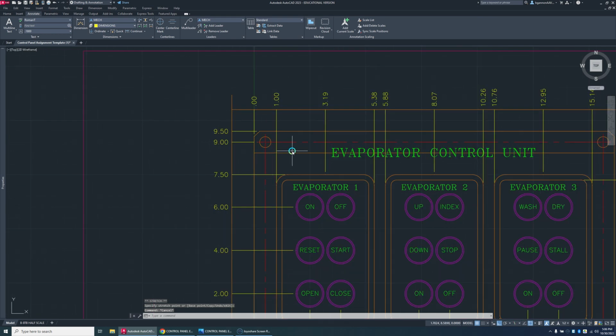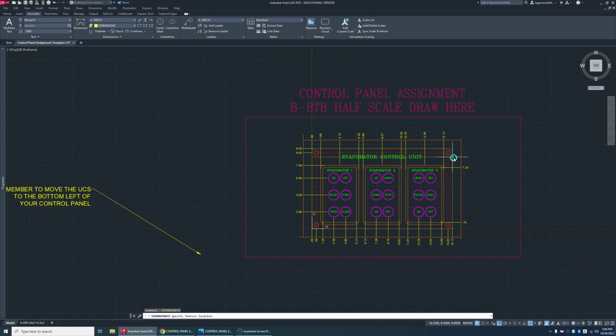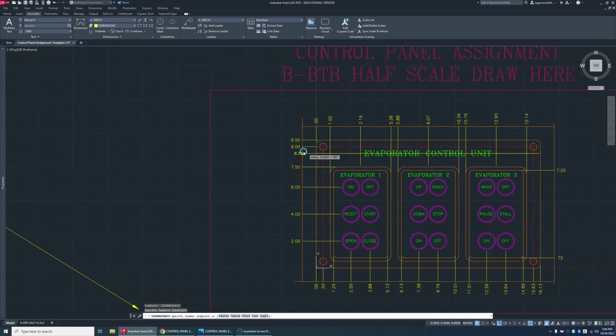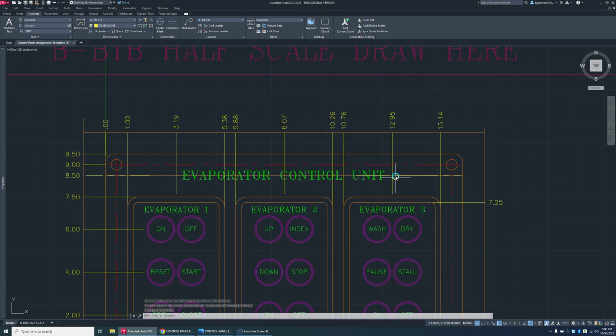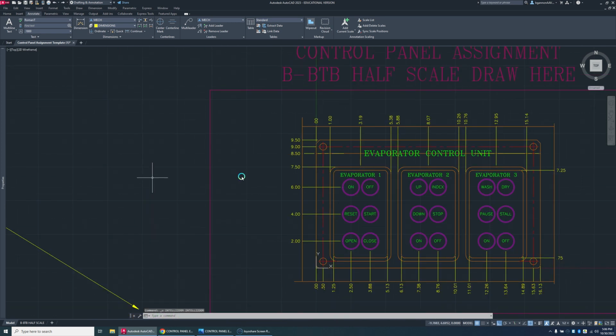Go across. Okay, then I'm going to add a dimension on that. So ordinate dimension, and go to here. I'm actually going to go all the way across this one, right there, like so. And then what I can do here is take this and break it up, break, and boom. I select I want to break it, and you can see it breaks right across all of that text besides that one right there. Control do that, and do that.